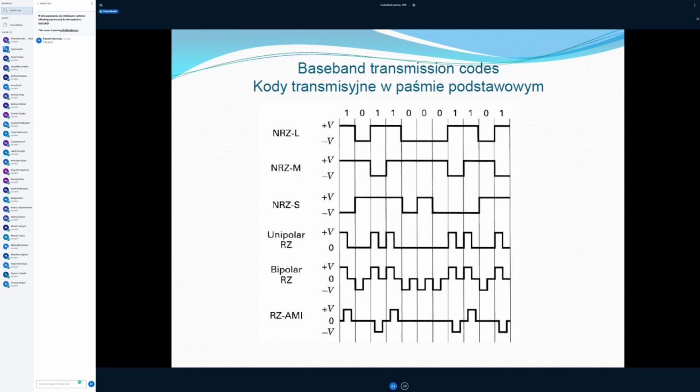So the clock looks like that, in one bit you have 2 changes of level. But it is not so good, because when you have ones, you have the impulses, and when you have 0, nothing is happening. So when, for example, you have a long time of 0, then your system does not have any possibility to synchronize. It is the same with those 2 codes, NRZ and differential NRZ.